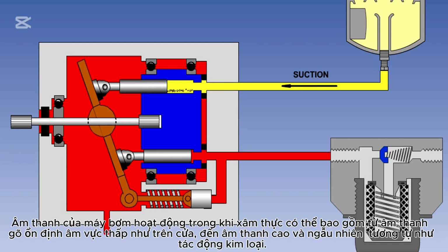The sound of pumps operating while cavitating can range from a low-pitched, steady knocking sound, like on a door, to a high-pitched and random crackling, similar to a metallic impact.